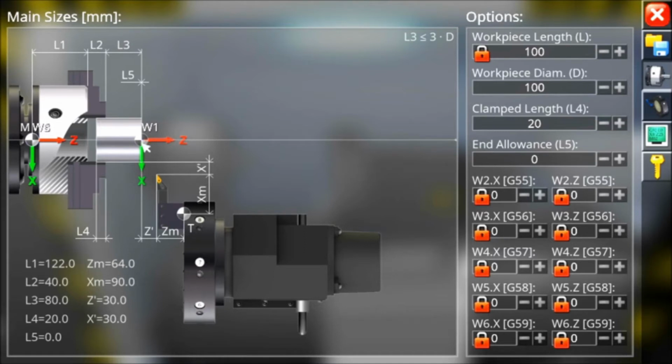Moving towards the tool we go from 0 to plus, i.e. X1, X2, X3, X4. Moving from 0 away from the tool we go minus 1, minus 2, minus 3, minus 4. Normally we work in Z minus, X plus.